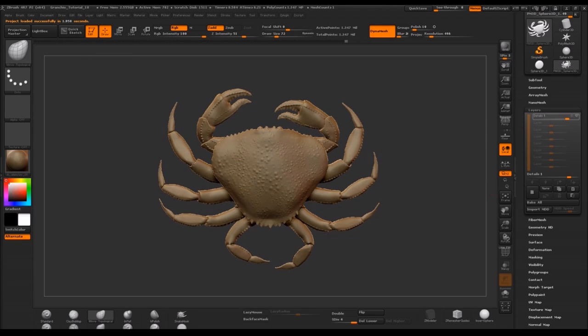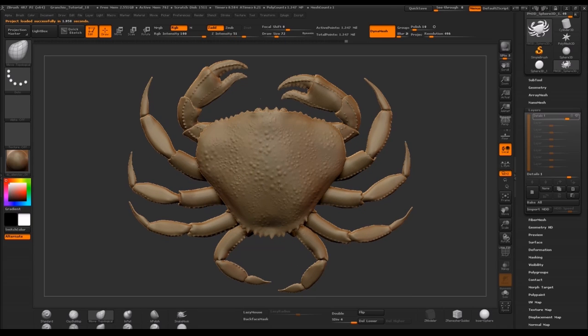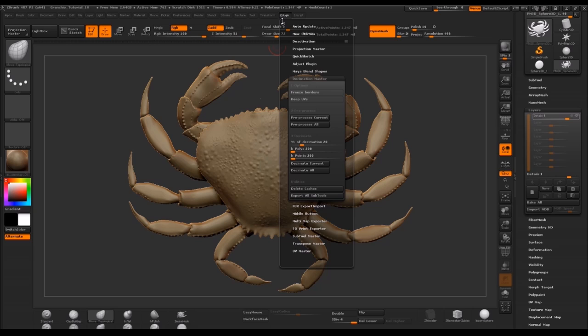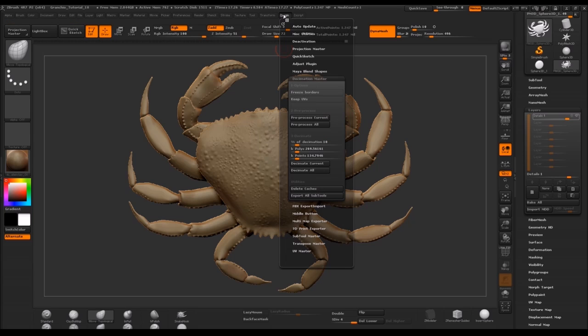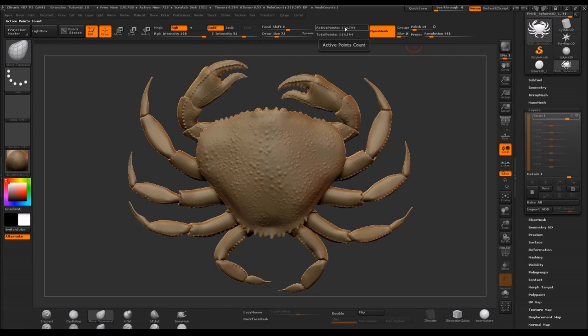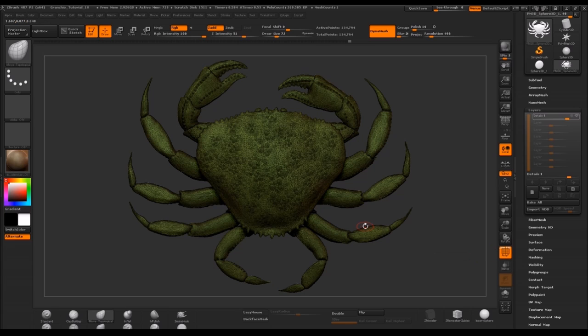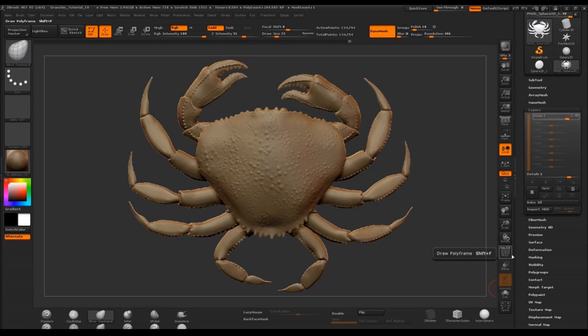The last thing that we want to do before rendering the model or exporting it to a printable format is to decimate it to reduce the polygon count without losing details. And to do this, we use a ZBrush plugin called Decimation Master that can analyze the model surface and reduce the polygon count by varying the size of the mesh triangles on the basis of the details it finds. The polygon count is a tenth of what it was before, but we have lost almost nothing in terms of details.